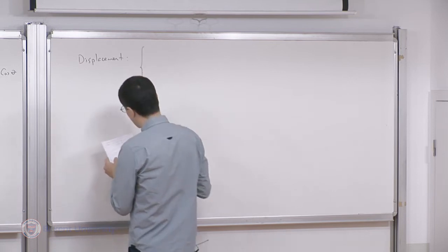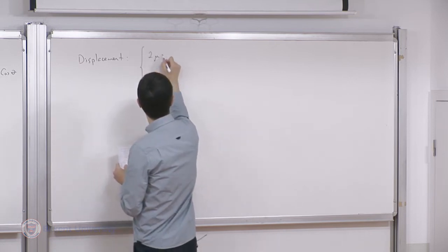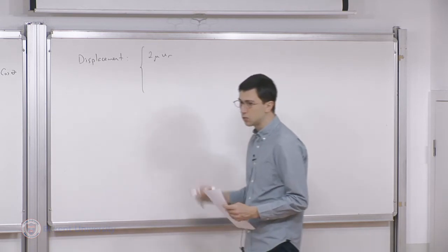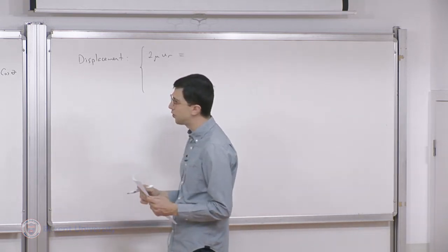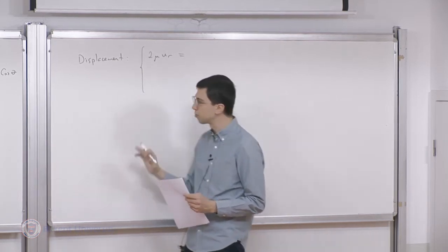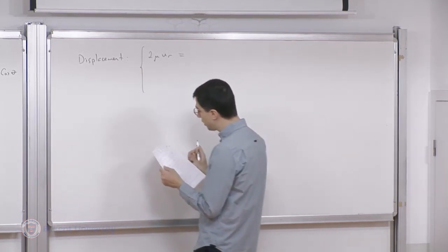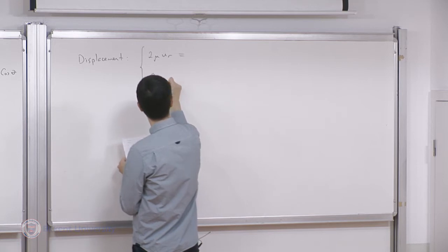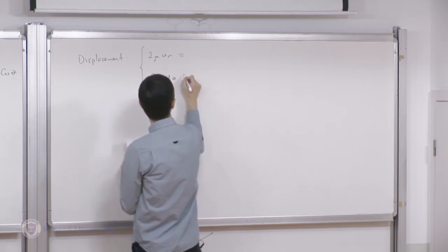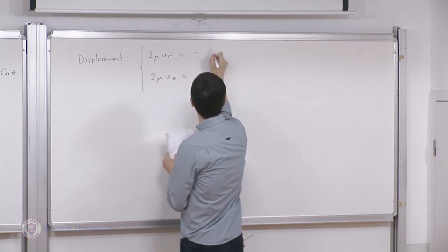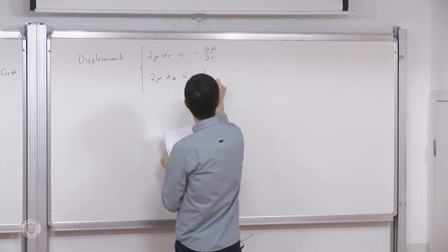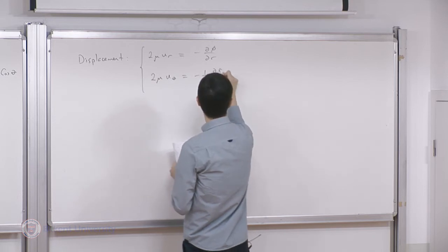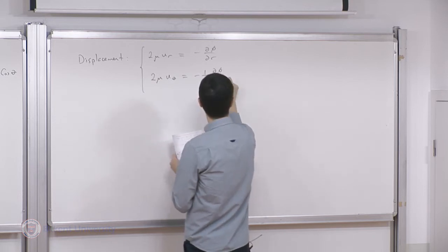So again, we are in a cylindrical coordinate system. I have to remind you what the appropriate relations are. Recall that the body force is negligible, so the equations that I'm about to write are special for that case. As usual, the first two terms of the displacements have to do with the Airy stress function.